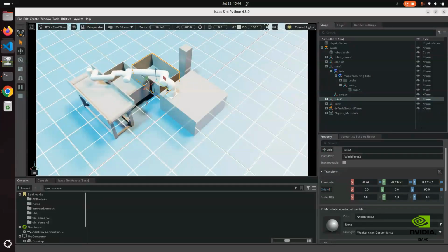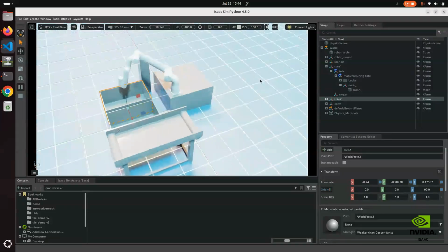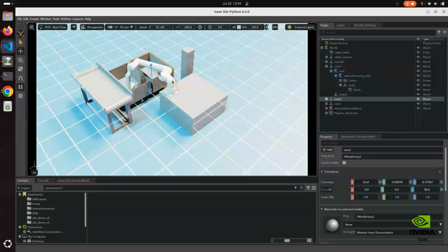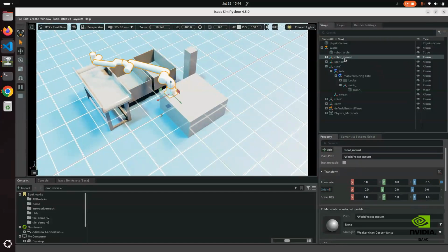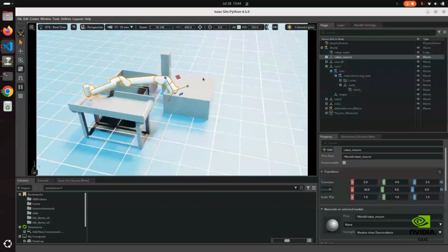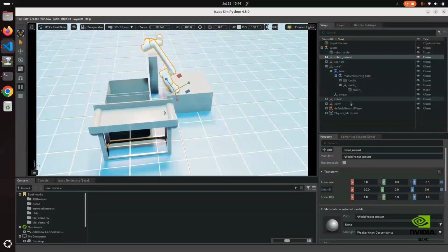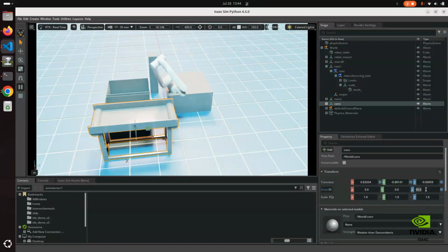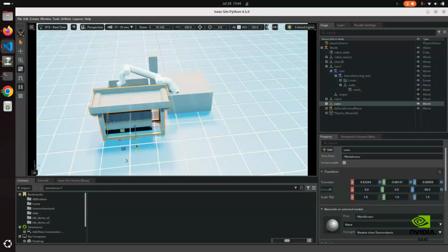Move the other tote out to match. So we don't want to be too close, and also it'd probably be hard for him to reach in on these very close positions. It still might be a little hard for him. Potentially we can adjust the robot mount like this. We could rotate that along the x-axis, potentially 30 degrees might make that easier. So he's now on an angle, and we're going all the way down to the other side of that conveyor belt. So let's make this -90.